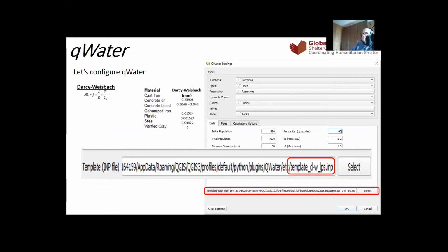Of course, in that case, I was choosing the formula of Darcy Weisbach. If you choose the formula of Darcy Weisbach, of course, then for the friction, you have to choose the right friction parameters. In that case, for plastic it would be 0.015.